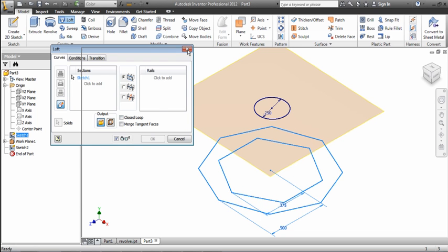So once we go into the Loft and we click the sketch, it'll light up red. I've clicked it, but I still haven't chosen a profile yet. I have to choose either the outside one or the inside one. So I'll choose the inside one this time. And now I can't select this next one here. I've selected this middle sketch, but I can't select it to loft to this circle here.